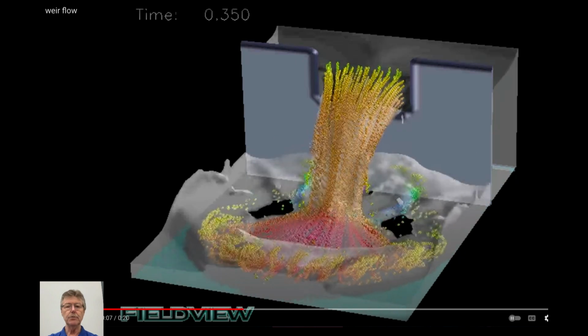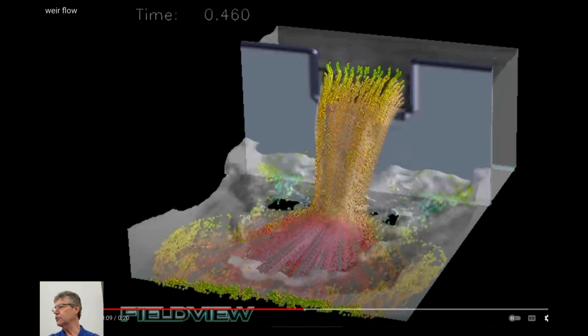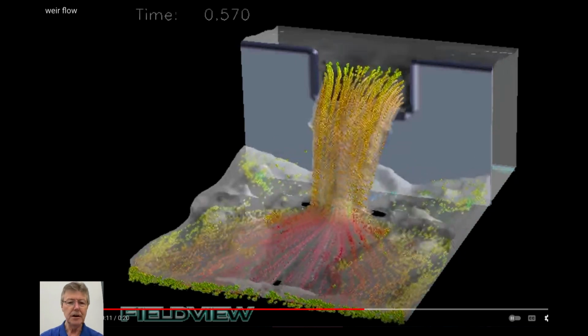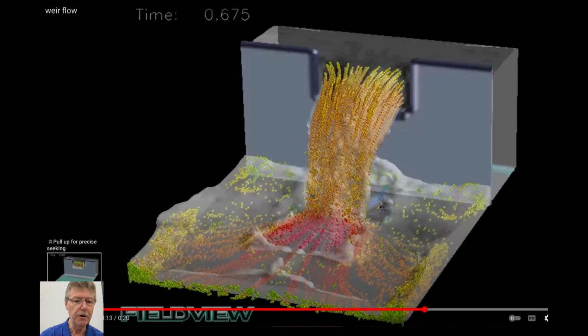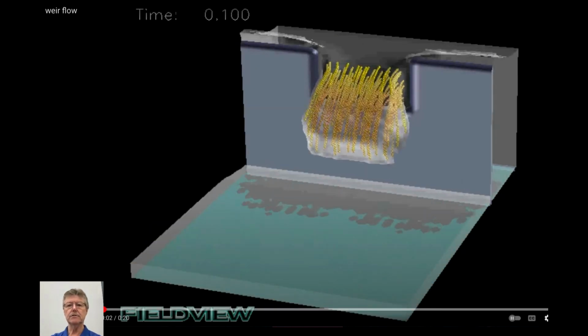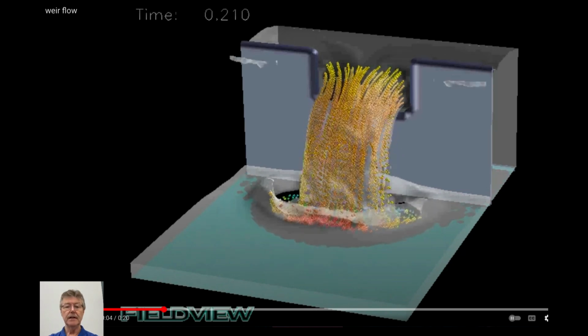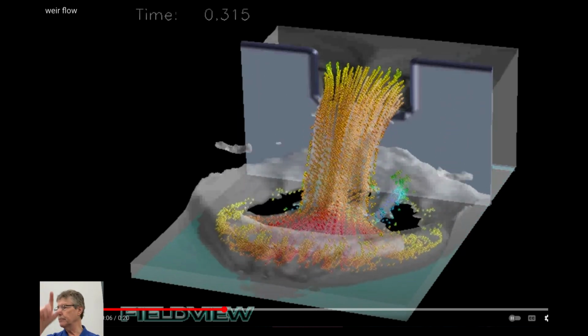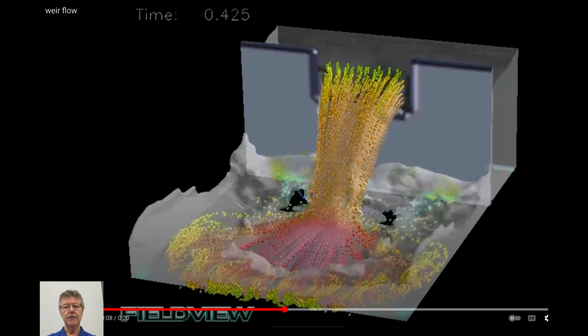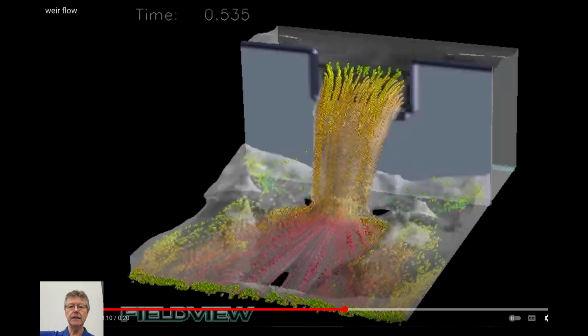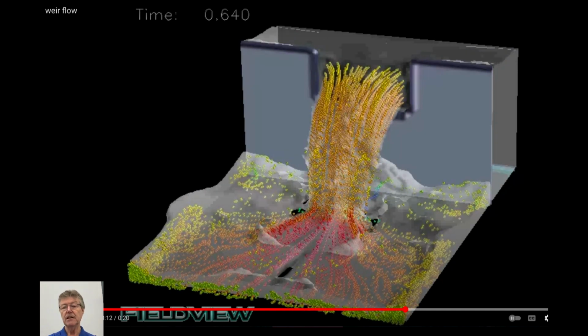So that's how you might make these measurements in a pipe. If you're out in the field and you want to know what the stream flow is in a little stream that's going across your plot of land that you're the engineer for, then a typical way is to put a weir across it. In other words, you dam it with a board. The board has a notch in it. The notch has an upstream head and a downstream elevation.